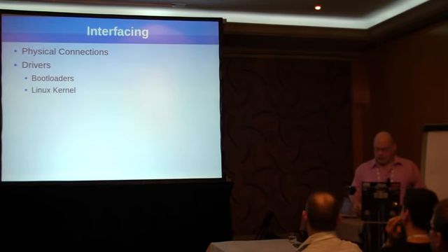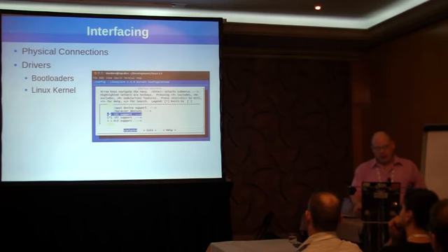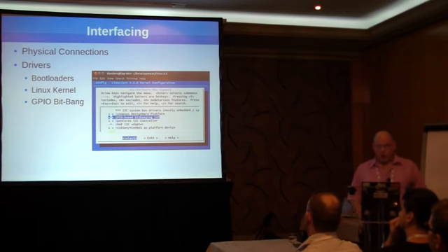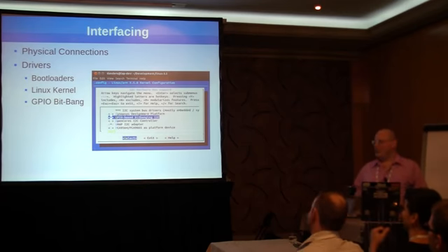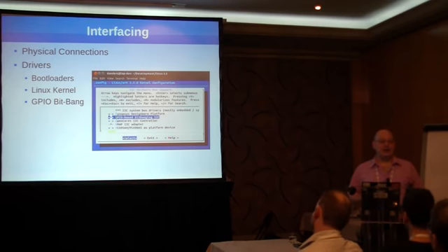The Linux kernel has had I2C support going back all the way to the early 2.2 series. However, with newer kernels, we have a class driver that supports a wide range of controllers and features, and it's very easy to set up. One of the things that's supported in the Linux kernel is a GPIO-based I2C controller.